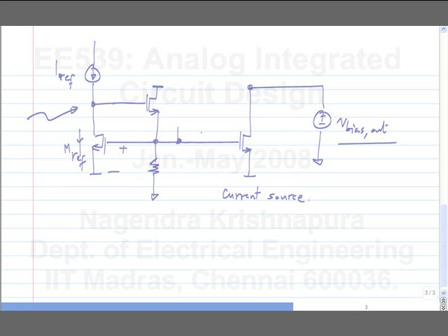First of all, to make a current source, what do I need? How do I make a current source? I will have to use a MOS transistor, right? Where will I get the bias from? So this is already a reference, right? That corresponds to IREF flowing through MREF. So I can connect it here.